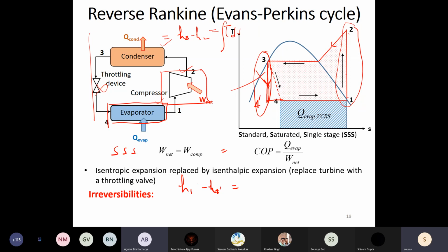Now consider a situation where you can have, let's say, 10,000 refrigeration ton capacity. Now over there, that 10% can lead to still, let's say, a few tens or hundreds of kilowatt. There it still makes sense because you are still obtaining some power of the order of 10 or 100 kilowatt by placing a turbine over there or an expansion device which is providing you some work output.